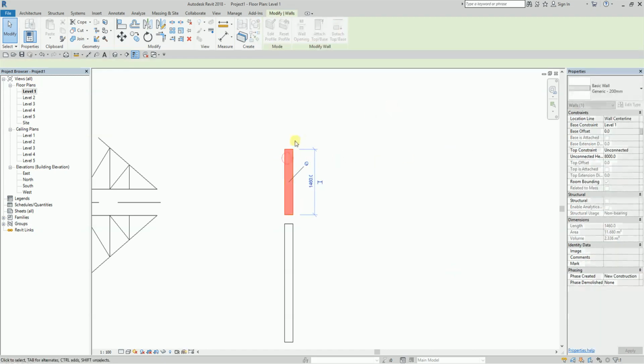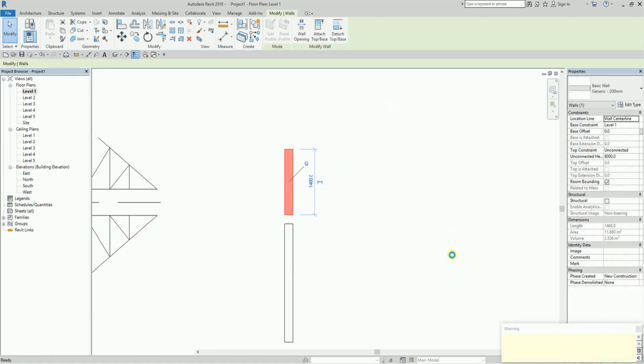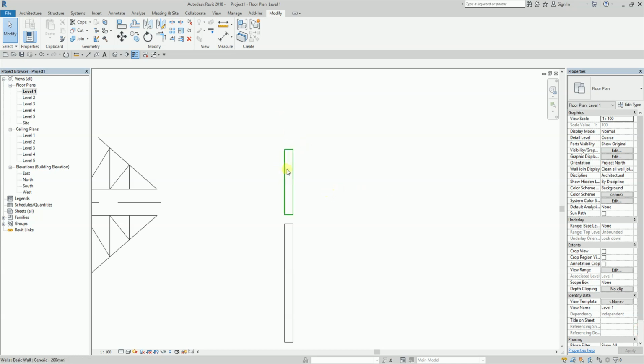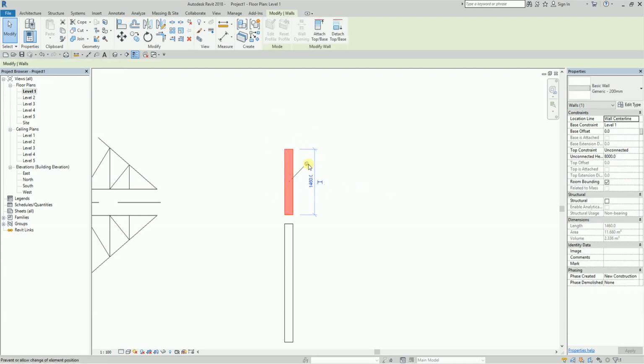There you go. So you will not be able to move that. Even delete, you will not be able to delete that particular object. As you can see, pinned objects were not deleted. So to delete them, unpin them before using delete. Now to unpin, just select that and then select this icon here, or you can select this tool here. All right, there you go.